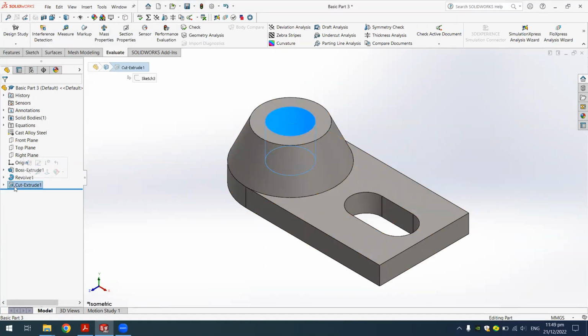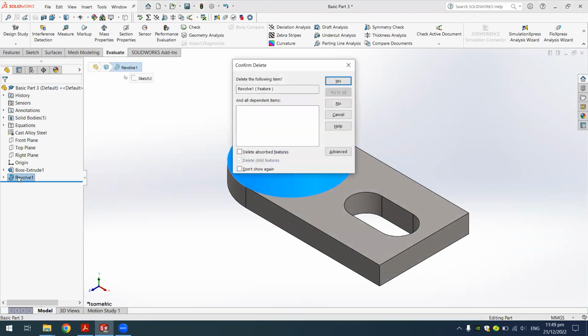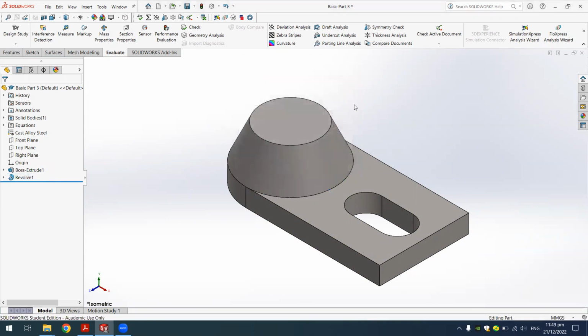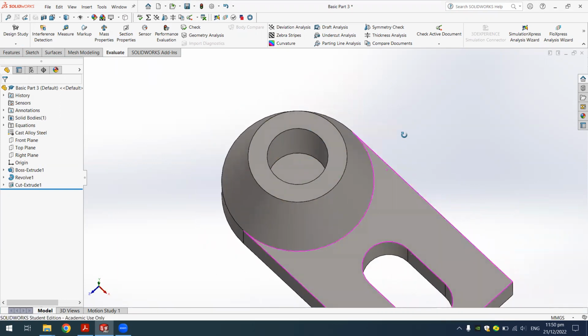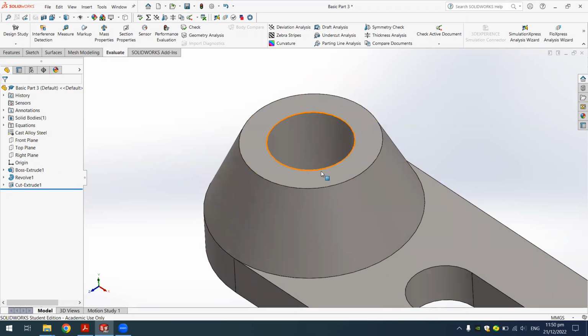Before I end, I wish to introduce another method, because just now what we did is we revolve cut a solid body like this, then after that we dig a hole through it. But it's possible to finish the process in one step. Because this hole is also a circle, in other words, this hollow cylinder can also be created using the revolve function.